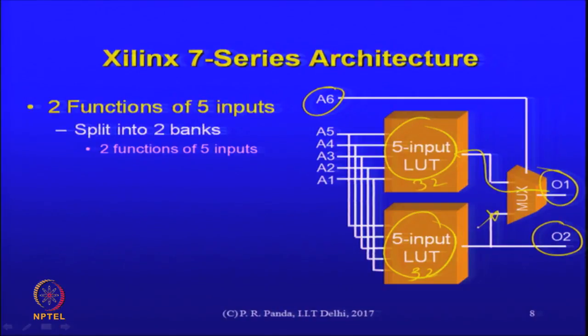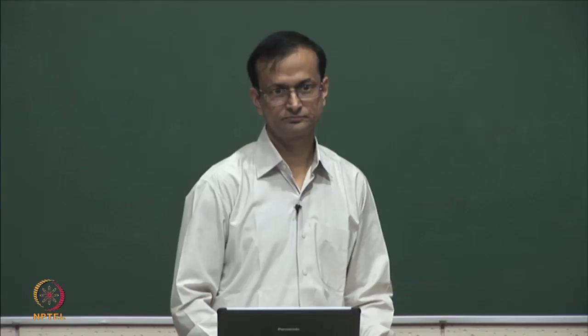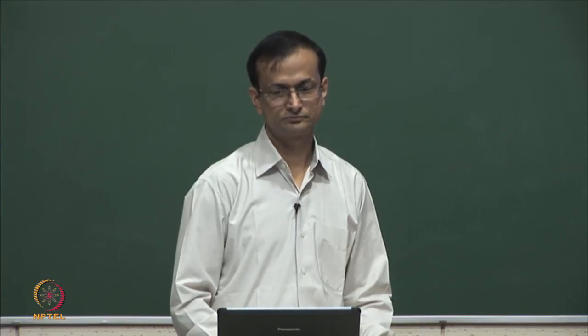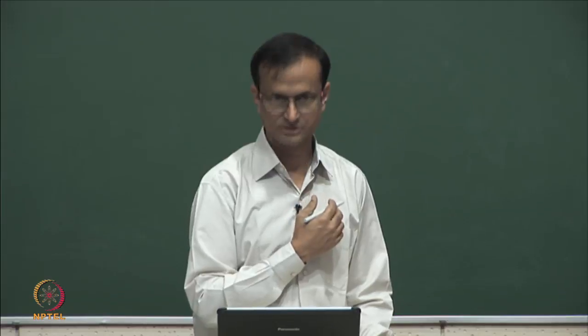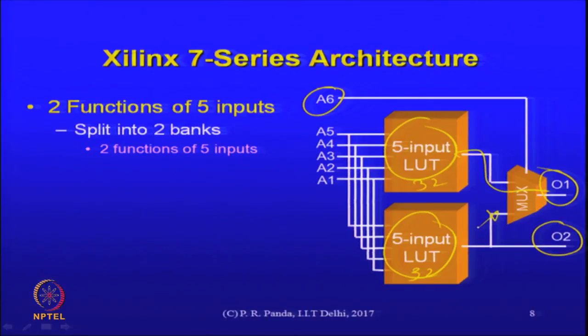In a typical CLB, I have not seen one, but I was guessing that if I have a 64-bit LUT, all my decoder for memory is sitting before the memory, not after the memory. But in this case, we are saying that either we have rerouted or something, but within the CLB itself, I could shift that decoder, that is the last decoder of A6, the MSB, after my memory, which is counterintuitive to me because the hardware is fixed in most cases. Oh, no, this is what the hardware looks like. This isn't a theoretical one, this is taken from the Xilinx hardware. This is how they implement the CLB.